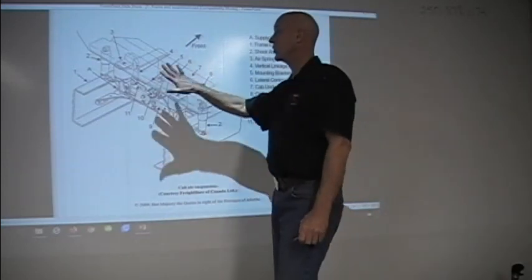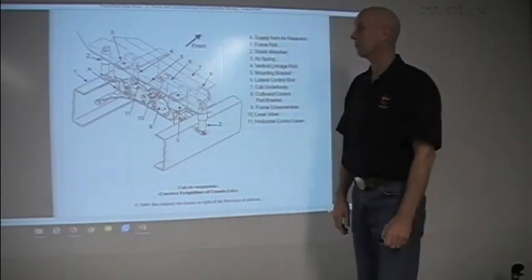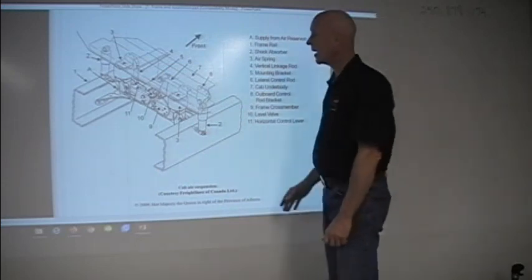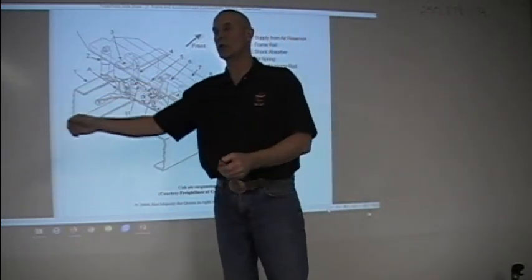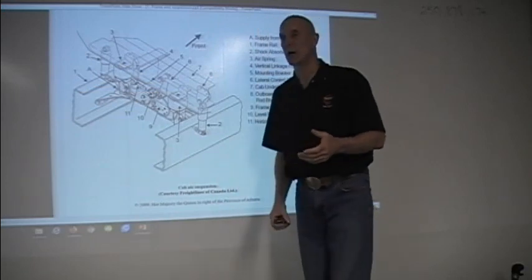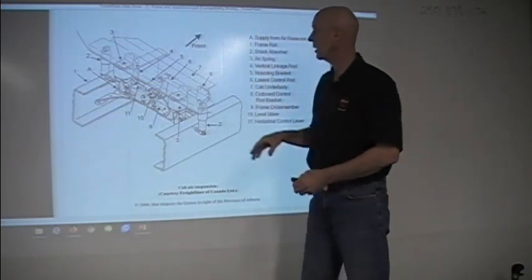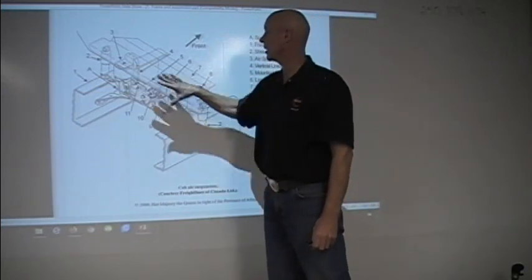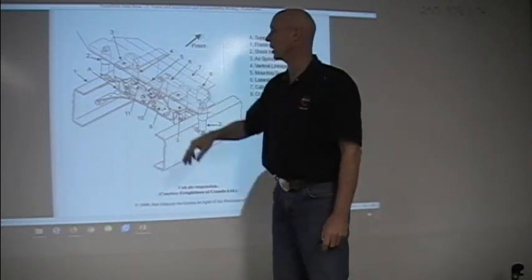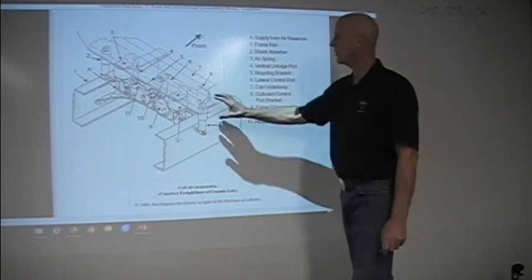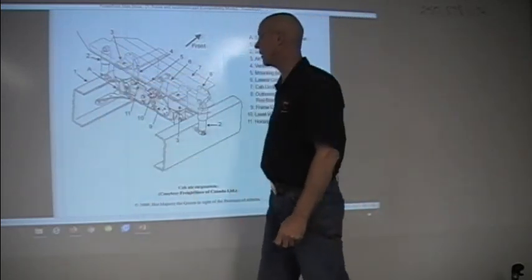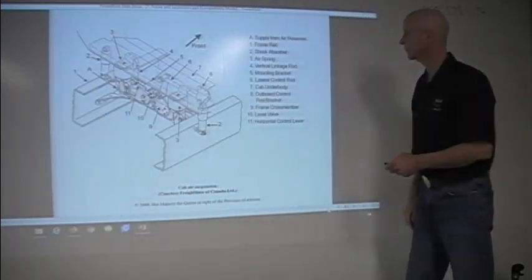We will also see air ride cabs now. So in an air ride cab, our front portion of our cab has got pivot pins so that the cab can move up and down. And again, we might have a single airbag or a double airbag on the back with a leveling valve. We also have shock absorbers again to prevent the cab from oscillating. And that's it.